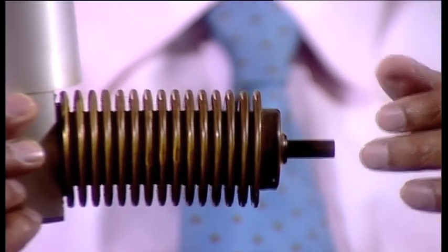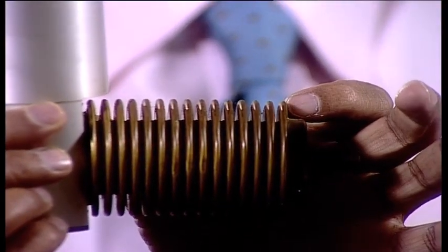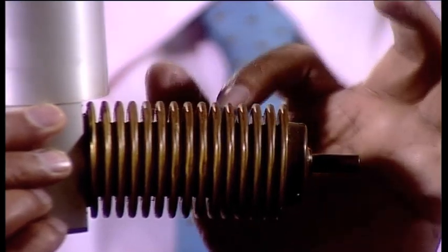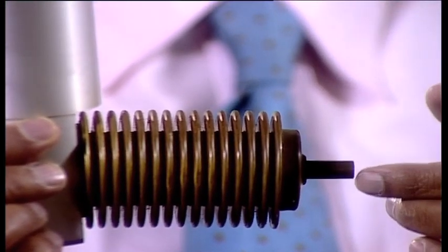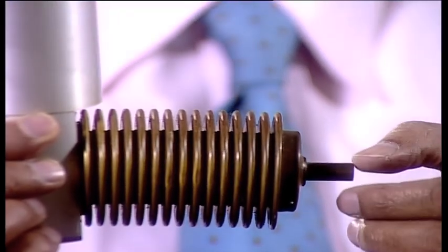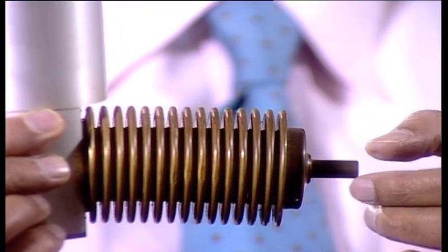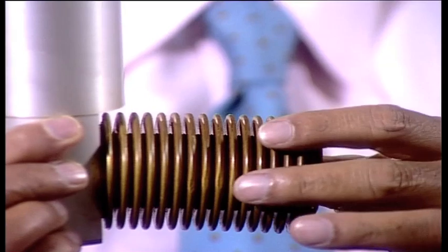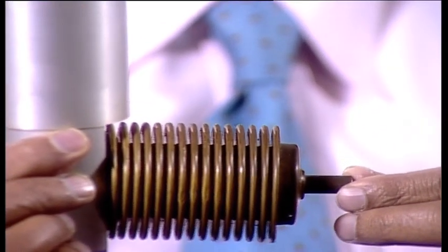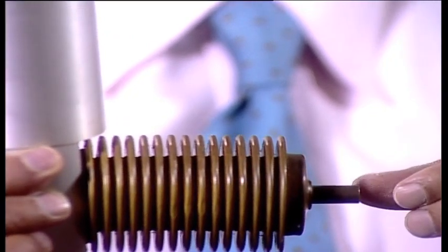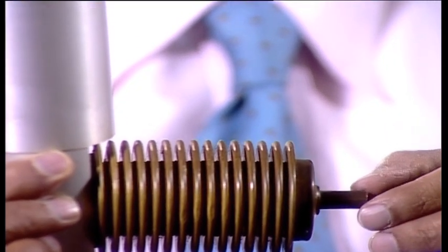You see, what will happen if this is hermetically sealed in the refrigerators? This is typically used for temperature control, because I can use this particular contact point for the temperature control. Then what will happen? If the pressure decreases in this sealed unit, it will squeeze like this one. If it squeezes, the electrical output will be disconnected, right.